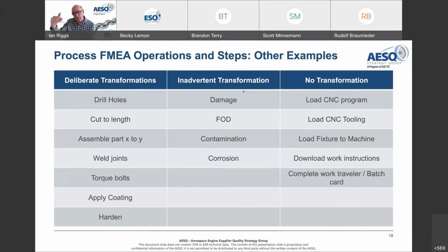Well, the logic would be, if you do that for one feature, you now have to include that on all of your features. And that's just going to generate an awful lot of lines where the answer is going to come back, well, make sure it's calibrated, make sure you passed an MSA. So we should avoid trying to put in things like the measurement system measured it wrong, or the inspector got it wrong, because you could put that on every single line item and just generate lots and lots of noise that stops you seeing the real issues.